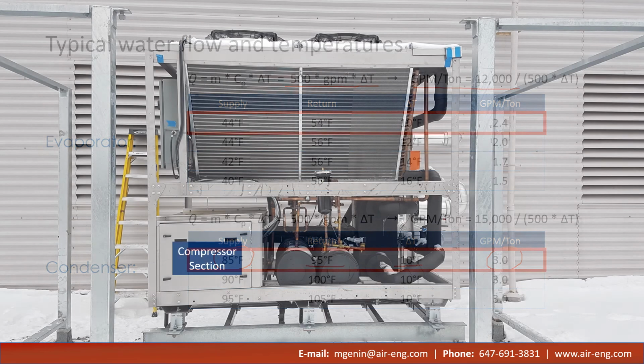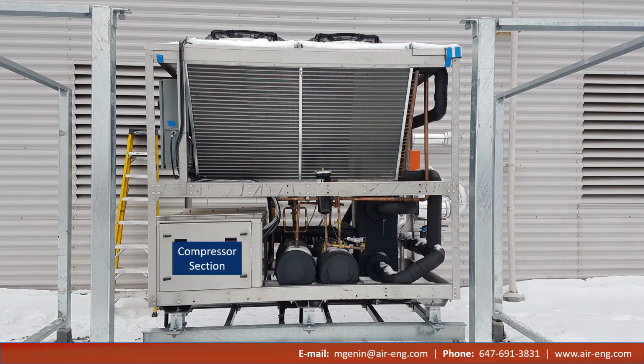This is an example of an air-cooled chiller. It's still considered a water chiller because it ultimately produces chilled water, but instead of a water-cooled condenser, it has an air-cooled condenser. We know that this is a DX air coil and not an evaporator coil because it does not have the unique distributors and capillary tubes that evaporators have.